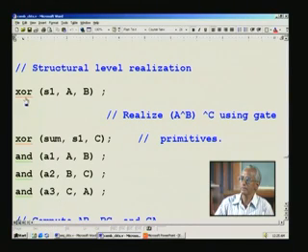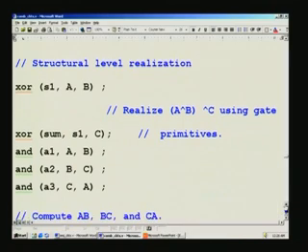Note that this is an output and these two are inputs for an exclusive OR. If you want, you can say U1, which will instantiate it, and there is no need to put it separately here. You can put a comma and add one more, U2, like that. This is what is realized here, exclusive OR of 3 inputs. Then A B, B C, C A, the majority logic for the output.